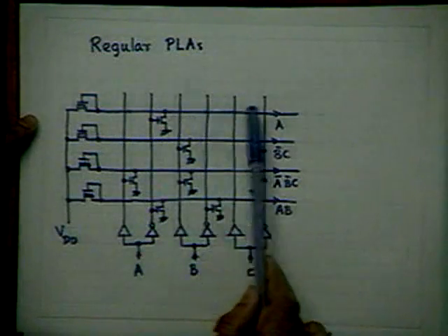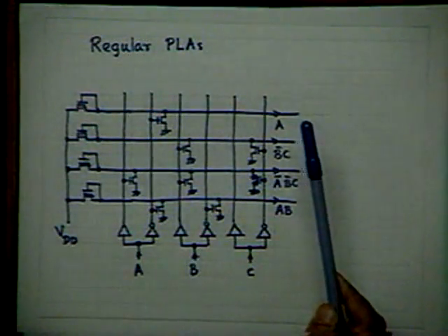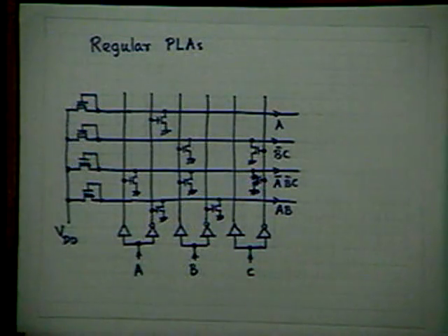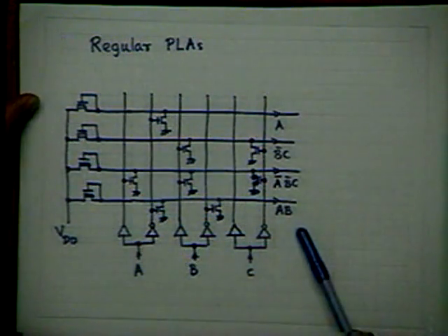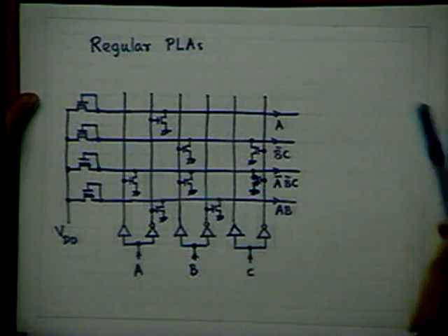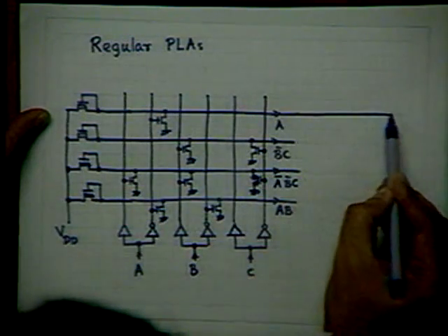I am again reminding you that the transistors are already existing. Only at the latter stage of fabrication, for etching holes and metallization, you connect them. Otherwise, it is existing. So fabrication is very simple. Even design-wise, it is very simple. But design-wise, we shall discuss that later. Then ultimately, I have to NOR them first and invert them second to produce my function. So again, I now extend the 4 lines.